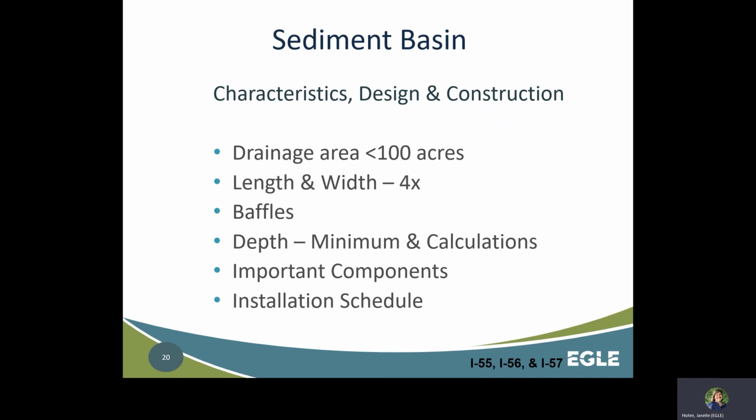The outlet from the pond may be a standpipe with a gravel collar or a spillway. The outlet must be stabilized and an emergency overflow should be installed in order to prevent erosion in the case of an extremely large storm event.